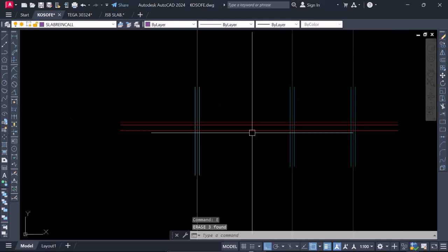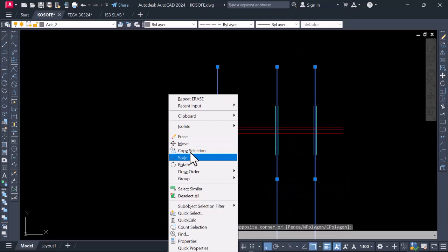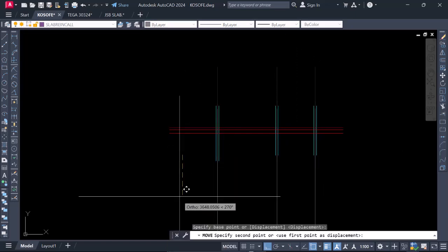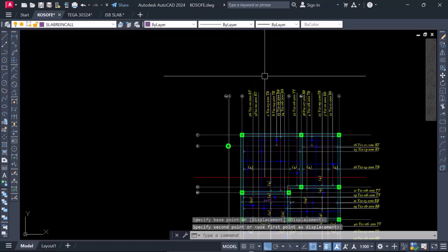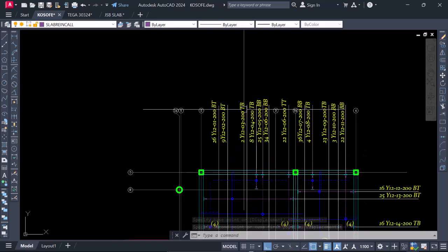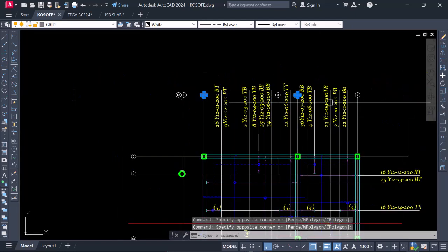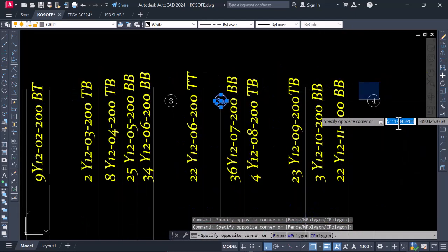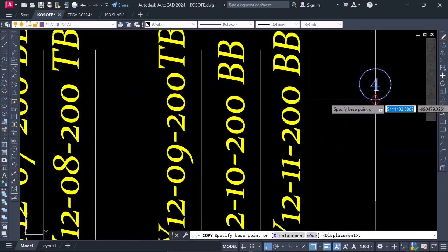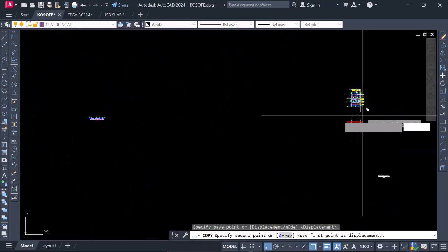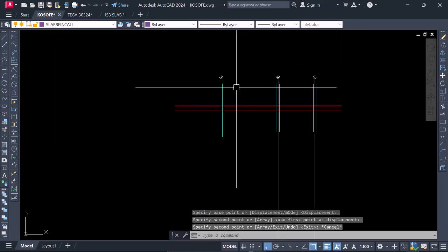So let's go back to what we are doing. Having these, we're going to trim over here. Let's try to move this down so that later we're going to just pick up our grid. Cutting it at this section, we're just going to highlight this. This is where you have your grid, because this grid is going to come with your structural plan. You can copy any of this grid from your structural plan. You don't have to worry about that. Paste it here.